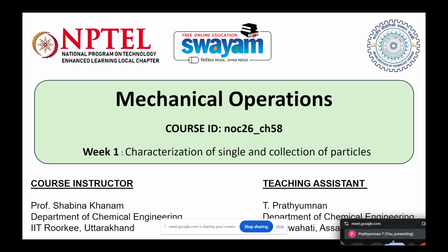The major reason why an optimum particle size is required is that only then will we be able to get a good viscosity, and that's when you will have a proper mouthfeel, or you can actually enjoy the taste of the chocolate.